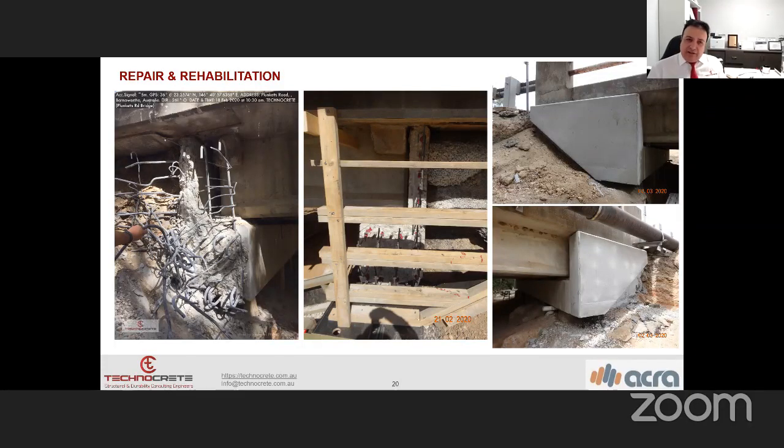But for the other defects, it depends on the quality of the concrete. I mean, we need a little bit more information in order to judge or interpret the tests which we have to do and the deterioration mechanism involved with the structure. For soft water attack, we have to investigate the corrosion and the concrete quality. These are the types of non-destructive investigation which we have to do. We need more information.